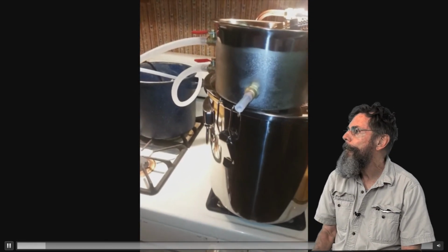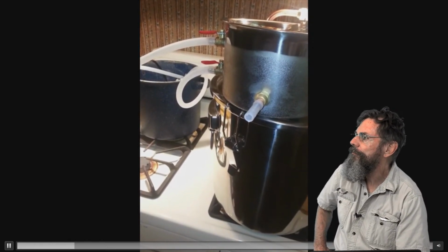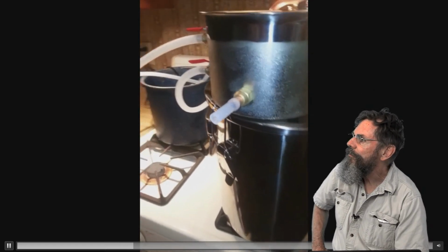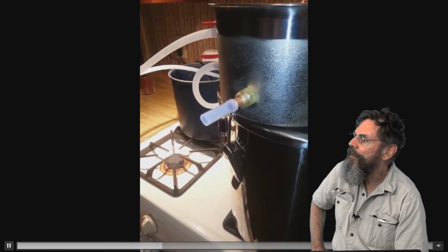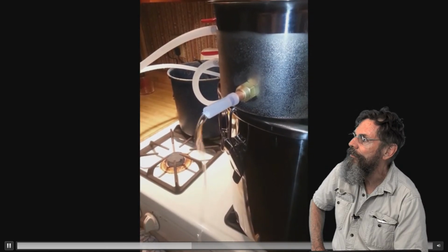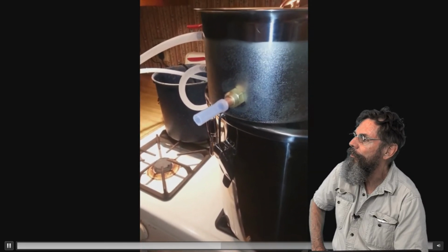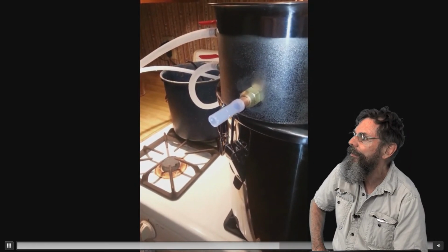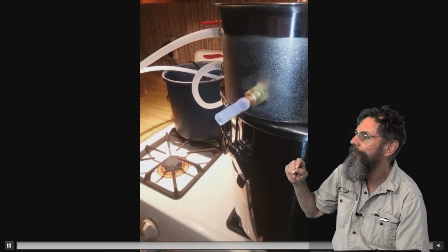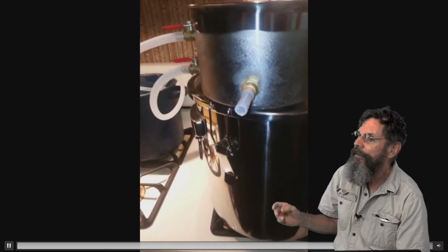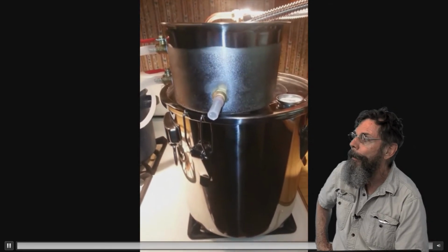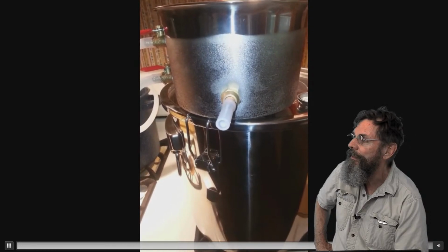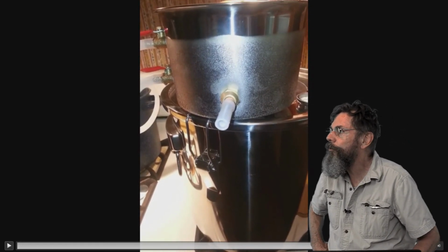Yeah. Now, what I wanted to do, this seems to be stalling here. Ideally, it's going to come out in spurts, and that's a sign of it actually working. It passes a little bit out, and then it catches up with itself and spits a little bit out. That means your temperature is at about the right level. If you turn it up too high, it's going to come out in more of a stream, which we're going to show you in a second. But I just wanted to show you what it looks like correctly.